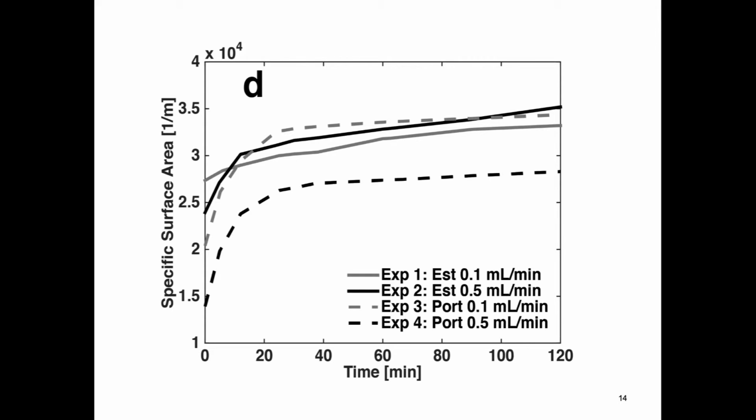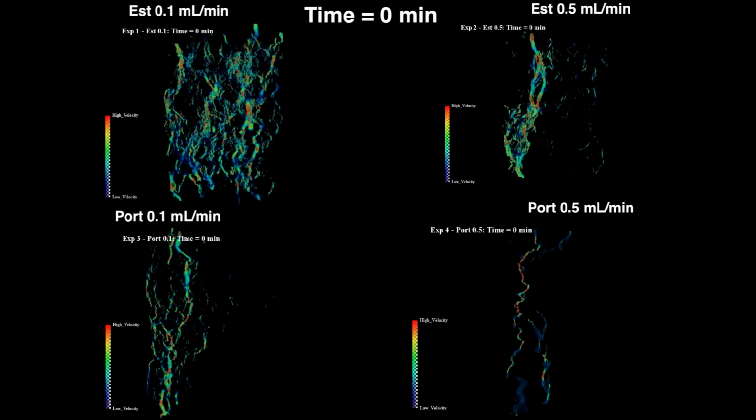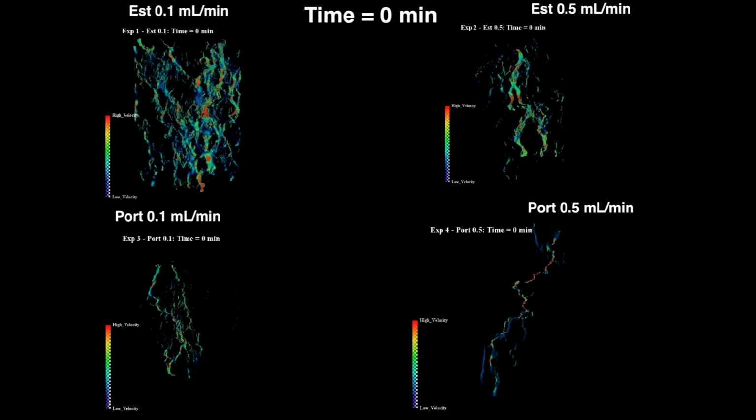Here, we visualize the ratios of the magnitude of velocity U at the voxel centers divided by the average pore velocity for Portland and Estaillades carbonate. U average is calculated from the Darcy velocity divided by the scan porosity taken from the segmented image. The Darcy velocity is constant throughout each experiment. It is imposed by the flow rate of the pumps.